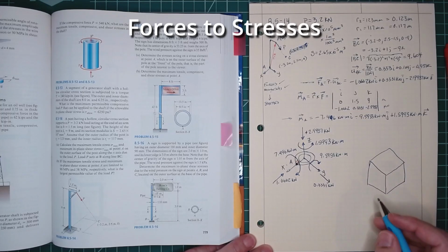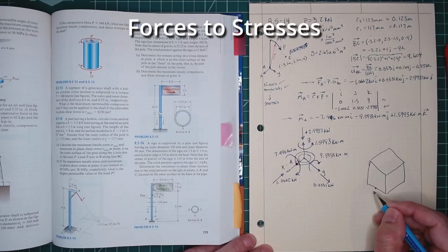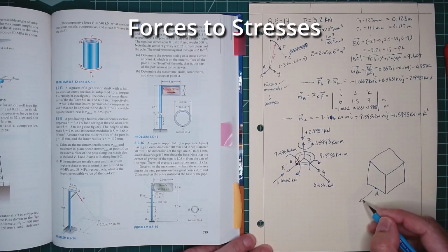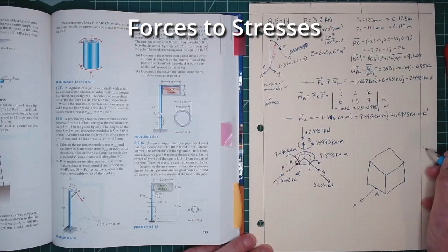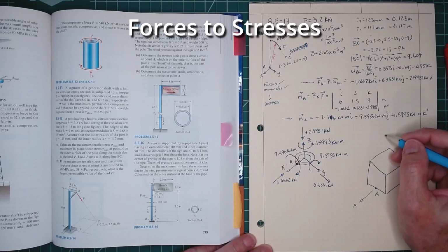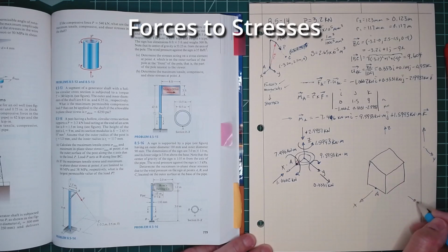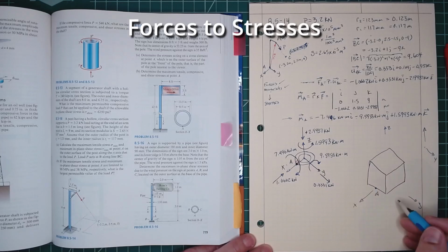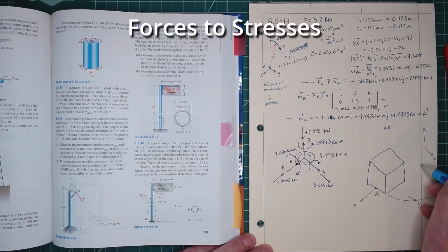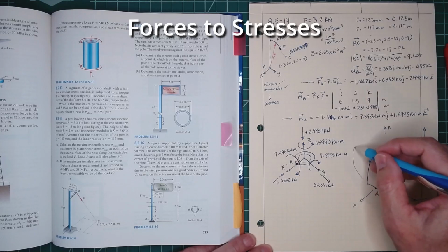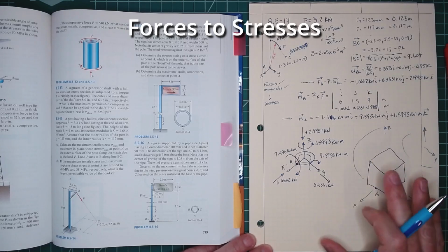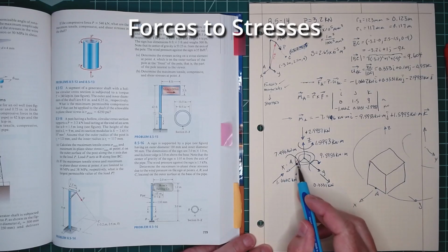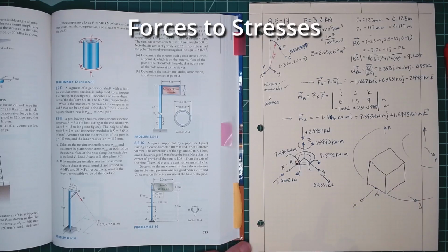Okay. So now if we think of this, this is really our point A. Our x-axis is here. Our y-axis kind of goes all the way back to the center, and then our z-axis, but our z-axis and y-axis directions are really the same here. So our z direction is going upwards, our y direction is going in this direction. And then our cross section, this is our hollow cross section. I'm just making this a little bit larger so we can see this stress cube, because we really need to identify the stresses that are occurring here.